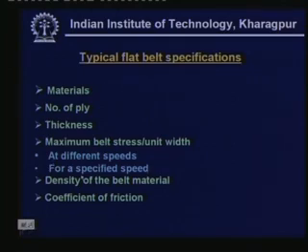What does this mean? This means that depending upon the belt speed, the tensile strengths also vary. So, the chart normally provided for design gives you the strengths at varied speeds, or it can give the strength at a given speed, and you have to incorporate the actual strength through a factor.